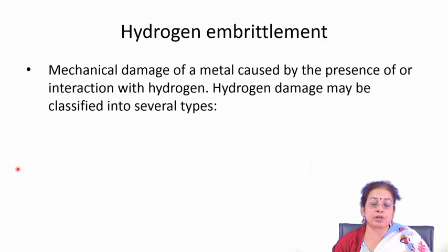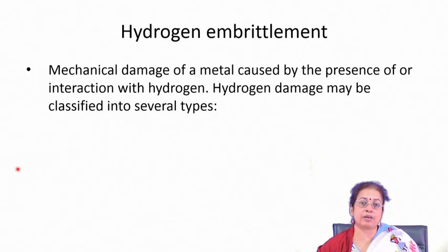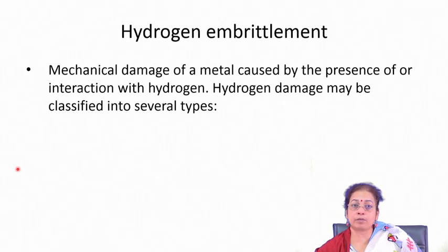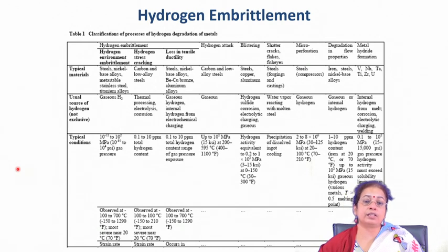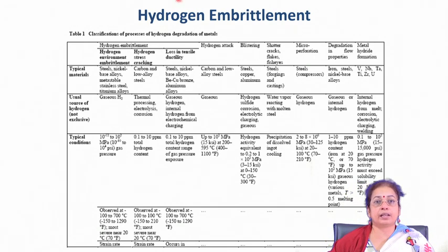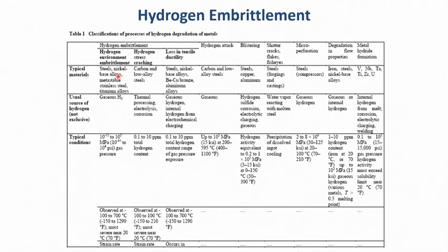and by that conversion process they apply a lot of pressure, and by that pressure you will find typical blistering inside the surface. That can also cause a lot of swelling inside the component, and that also causes the embrittlement of the component. So, if you see the different reasons behind this hydrogen embrittlement and their effect, there may be several, depending on the material. Particularly if you see the material and environment as well as the type of hydrogen attack observed in different materials, they are of wide types actually.